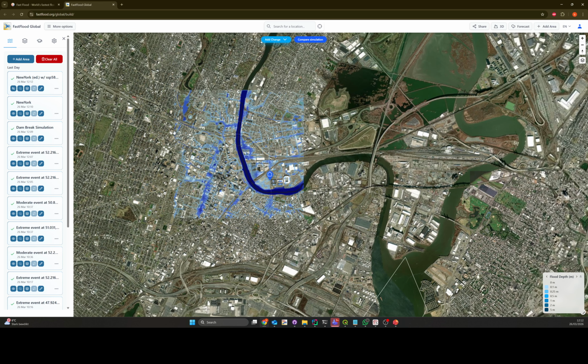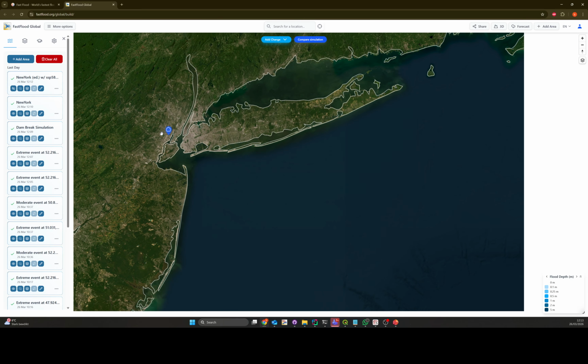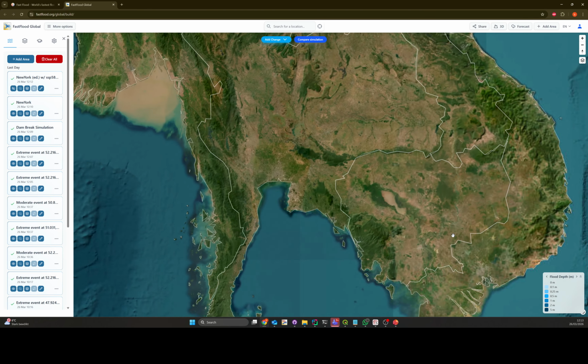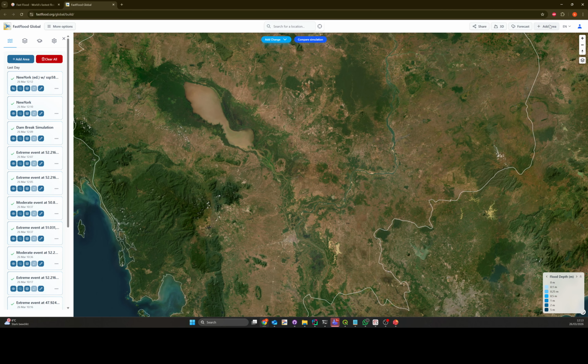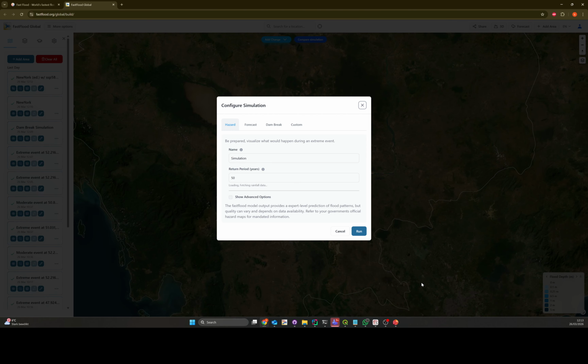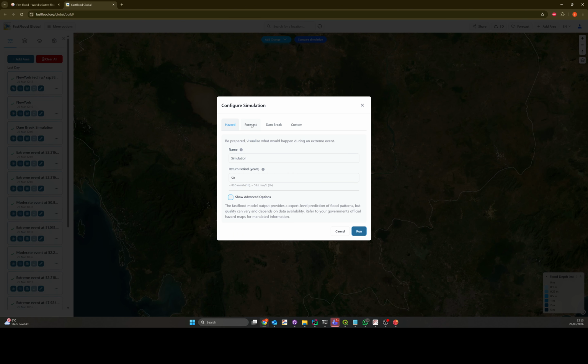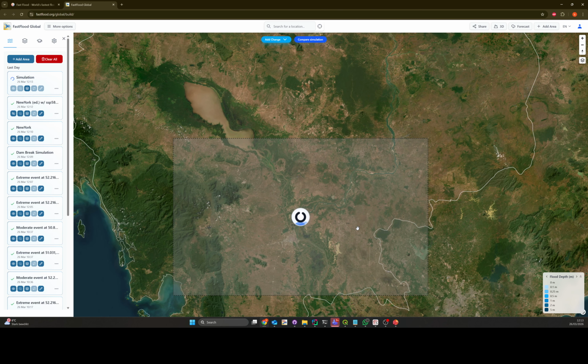Now, we deal with small and large areas. As I said, what might be interesting is to have a quick look at some bigger area. Maybe if we go to the top right and select Add Area and then Select, we can go ahead and select any domain. And then for the hazard map option, by default, it goes to 50-year return period, and we could specify the level of detail that we're interested in. For now, I'm just going to click Run, and it should generate for us, for this entire area, a 50-year return period flood hazard map.